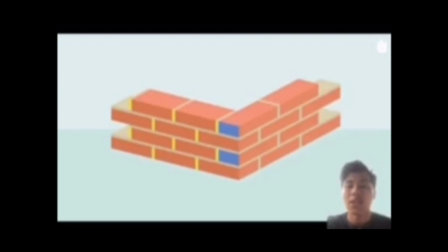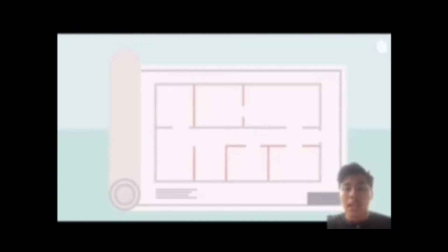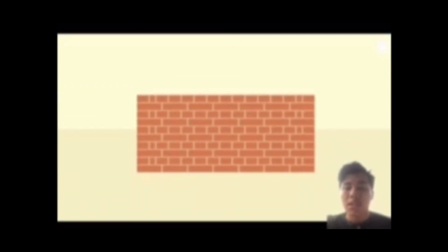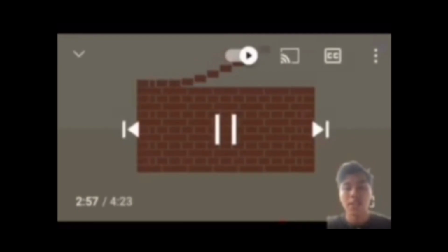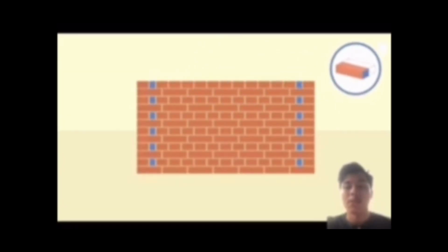When measuring the comparative level between two distant objects beyond the reach of the spirit level, you may place it on top of a straight edge to bridge the gap. If the bubble indicates an uneven surface, remove the spirit level and make the necessary adjustment before taking a second reading. Make sure that you take your reading from a right angle in order to avoid error. You have now learned to use a spirit level.